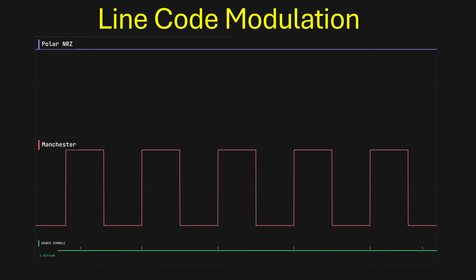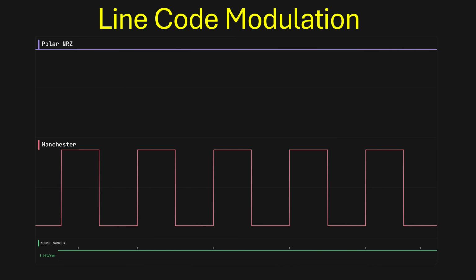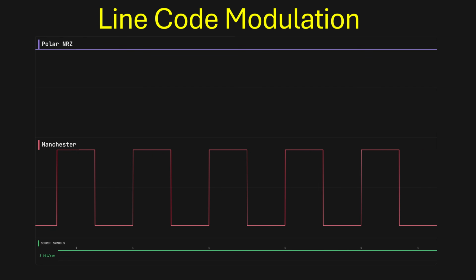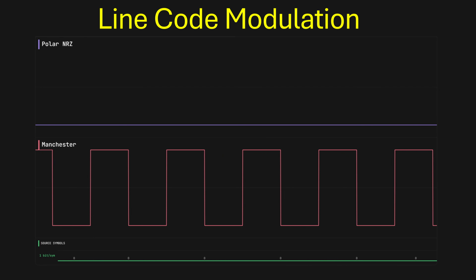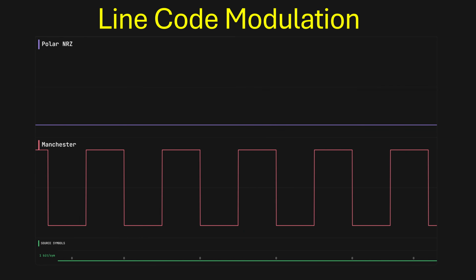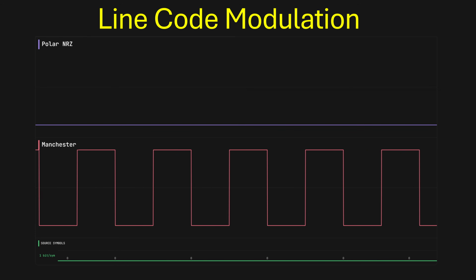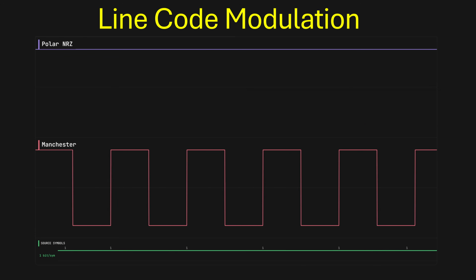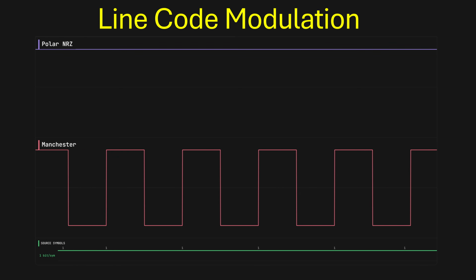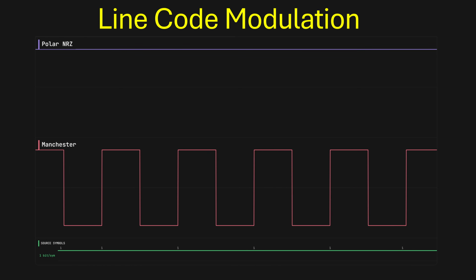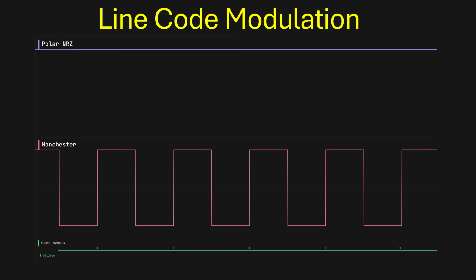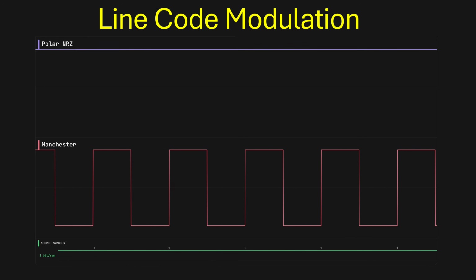An early solution to this problem was Manchester coding, which encodes 0 as pulsing on then off and 1 as pulsing off then on. This scheme doubles the bandwidth for the same bit rate, but the advantage is that for a long string of 0s or 1s, where there would previously be a constant direct current, for Manchester coding, it will alternate to synchronize the clock and balance the positive and negative voltages like an AC sine wave.